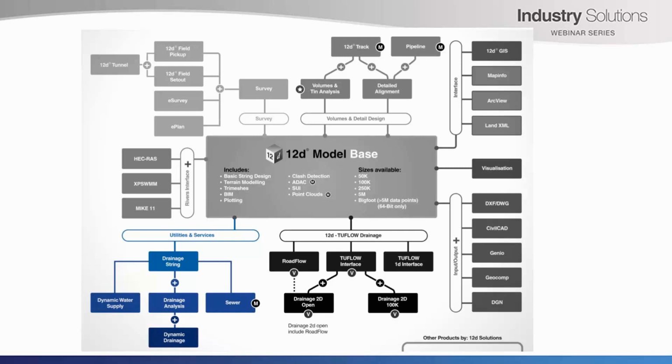The 12D model sewer module is an extension of the drainage module and supports the design of gravity-operated wastewater reticulation systems, typically those required for new land subdivisions and development projects. When satisfied, the design invert levels connections from the design line to the existing house blocks can be added and reported on. Special wastewater reticulation long section plots show the existing surface, manholes, design pipes, pipe grades, property connection points, and all obstructions.